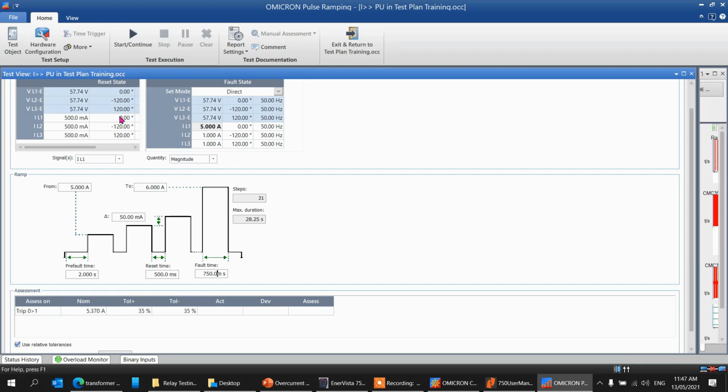For now, yes. But normally we can do it in just one phase, or two phases. If you don't have earth fault, you can do it with one phase. But if you have earth fault, then you have to do it with two, because if you do it that way and you are not tripping on the instantaneous but on the earth fault, then you get the wrong time. Then you have to identify what's happening. You have to step back and analyze what's happening, going back to the principles that we learned earlier.